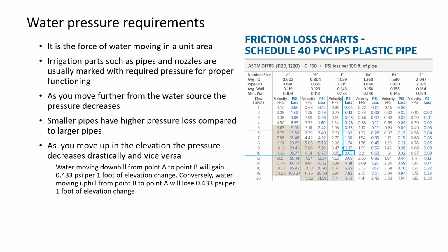Same thing when you are moving up hills, or if you are in a slope area, you will lose 0.433 psi per 1 foot of elevation change. So you need to consider that.